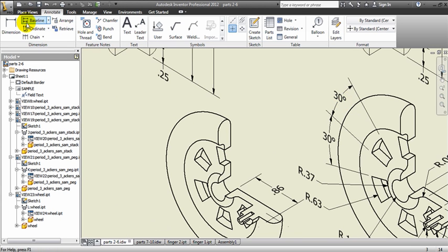For the degree ones, you go ahead and click one line and then click the next line, but make sure you don't lock onto green. Make sure it's line to line. And then just bring your mouse out and it'll give you 30 degrees. Same thing with these lines. 30 degrees. And line them up.